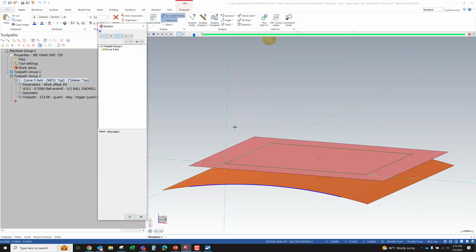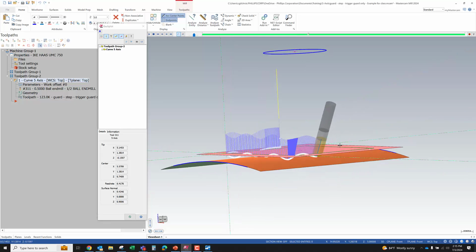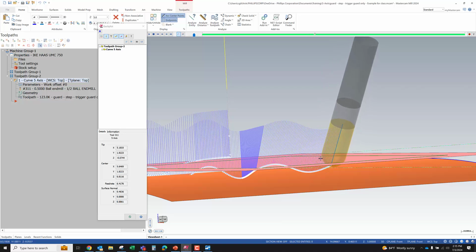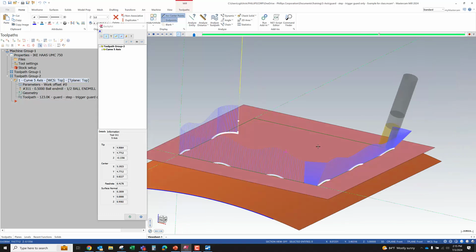And if you're cutting aerospace composites at Boeing, I can tell you we use this a whole lot because it spreads the wear of the tool, because those skins are very abrasive. So it spreads that wear over the flute length, and helps your tools last in many cases, sometimes up to 10 times longer, because you're not wearing just a wear line just where you're contacting that skin.